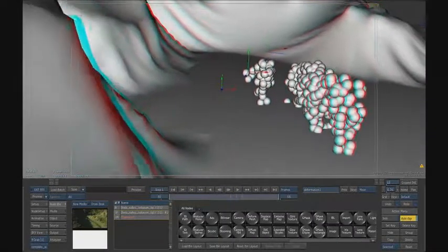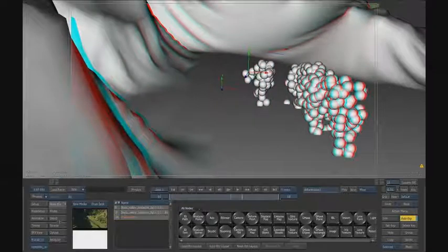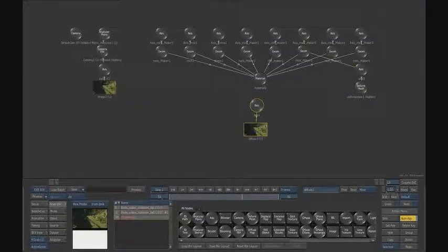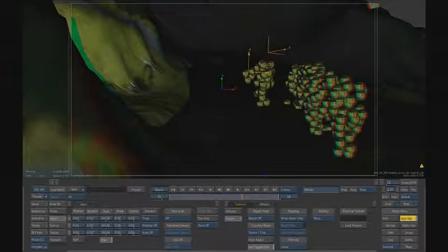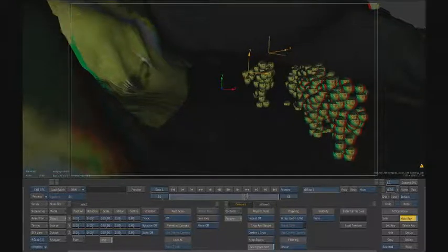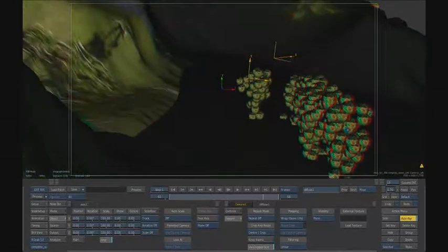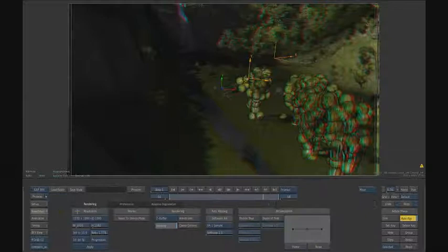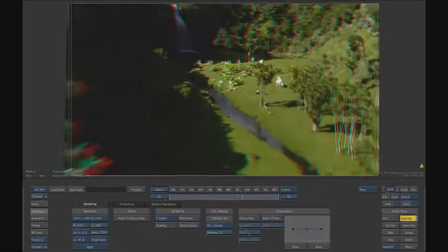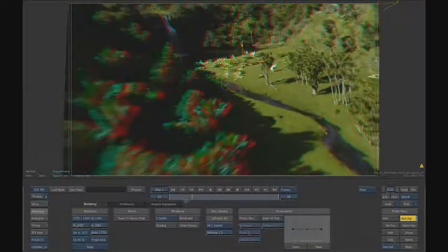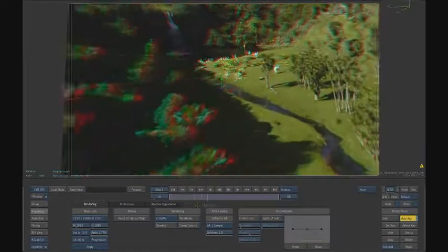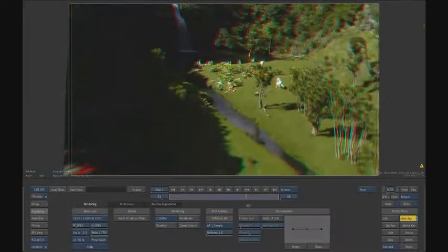What we'll do is we'll project our material on now. And that's done by using a diffuse map here, which is rather like a projector, where we can wrap the footage on. And then, of course, a default UV wrap is not quite what we want. We don't want each individual sphere wrapped with the image. We want a camera-based projection. And, of course, we'll turn off our shading or lighting in this situation so that we can get a result that looks like this.